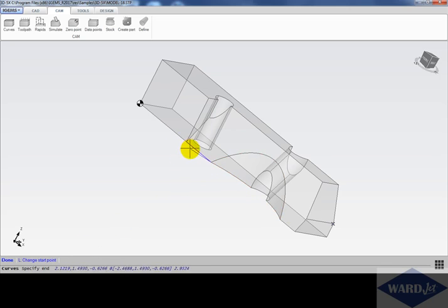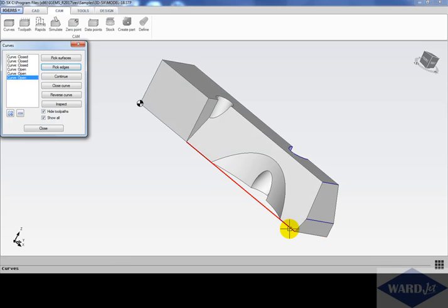And sometimes when you're doing your first edge, it doesn't know which end of the line that you want to start from. So if it selects the wrong end of the line, you do have the option here for L to change the start point. It'll move it to the other end of the line, which actually we had right that time. And then for the end point of the line, I'll just come over here and snap to the end point of that line there, and then hit enter, and then end one more time to get that there, and that's all I want to do. So that gives us that there.